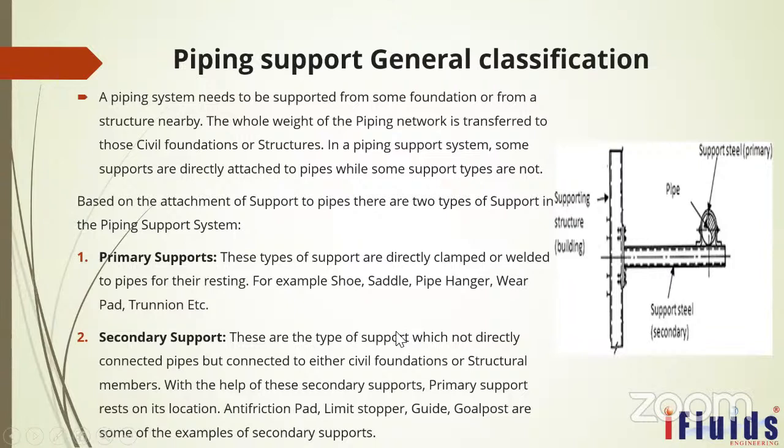On the other hand, if you look at a pump as the load, actually pump with the motor is a load. Pump is located on the base frame. That base frame is the primary support which supports the pump. That pump base frame will be supported by the anchor bolt, anchor fasteners, or some other foundation bolt or grade where it is mounted. That is called secondary support. Same for other equipment and pumps also.